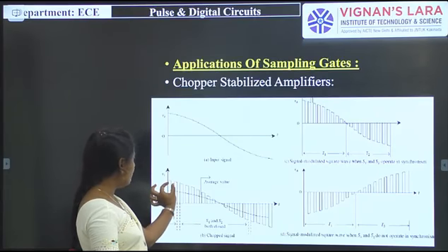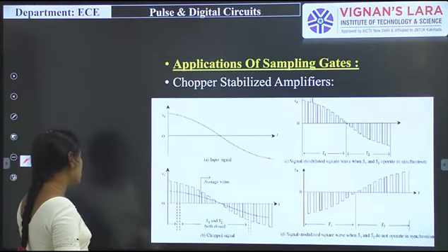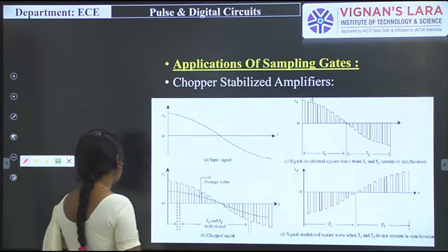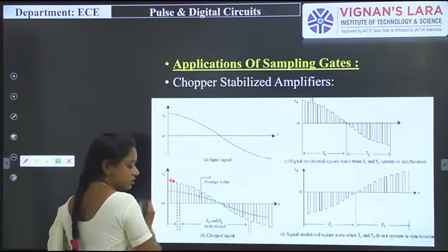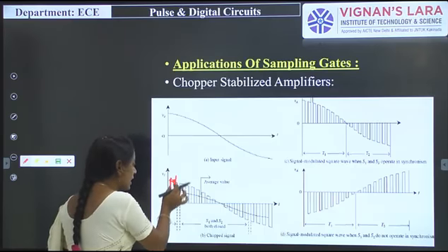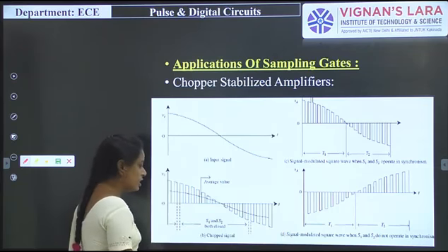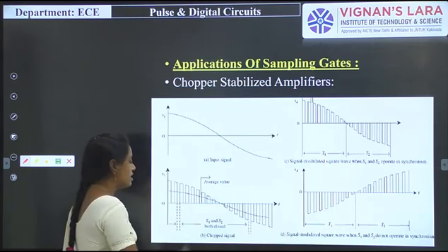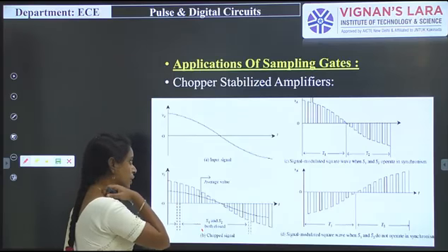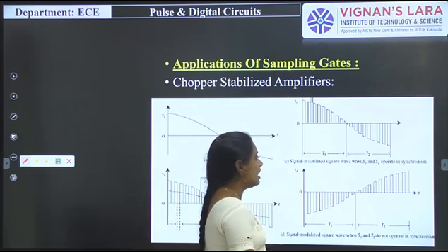The signal passes through this circuit. When the switch is closed, we don't get any input signal, and the remaining time we get the input signal. That is the condition when S1 and S2 are both closed. So whatever input signal we give will be chopped and modulated. That is the signal modulated square wave when S1 and S2 operate in synchronism.